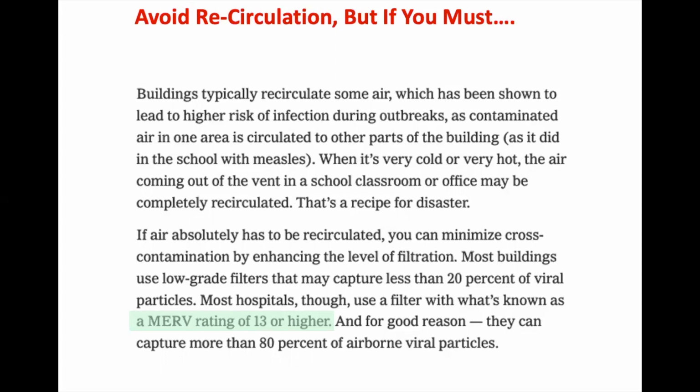One of the takeaways of all this is they're talking about going back to school, going back to the office, and I'm seeing all sorts of webinars that I've been sitting on by consultants and industry people and ASHRAE, and they're talking about these three metrics: more ventilation, no recirculation, higher filtration. They're talking about retrofitting existing equipment to do that. I'm talking about taking a packaged rooftop unit that's bringing in 20% outside air right now and turning it into a dedicated outdoor air system.